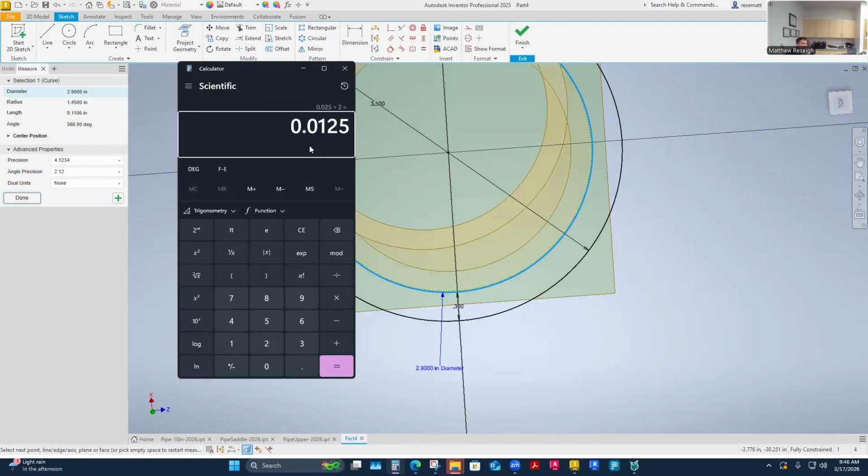The other problem is pipe sometimes comes with an inner seam, some weld junk in there from the way they weld pipe together. You can get seamless pipe that's way more expensive, or welded seamed pipe that has stuff in it. So if I buy this, I'm afraid I may have to have someone ream out the inside of this 3-inch pipe in order to fit the 2.5-inch pipe inside it. That could be bad.